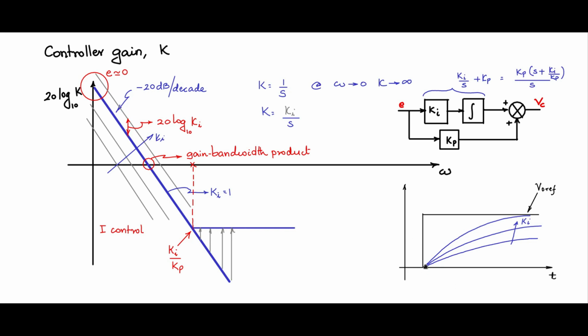The result is that in the time axis, this is the high frequency part, the transient part, and this is the steady state part. So you will be pulling up the transient part because the gain has increased. You will pull up the transient part. And then after it starts going to the steady state part, you will see it is only the I control that comes into the picture. The baton is handed over to the I control.